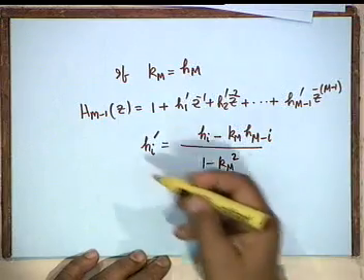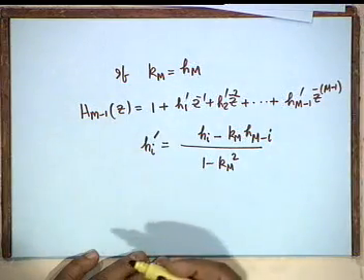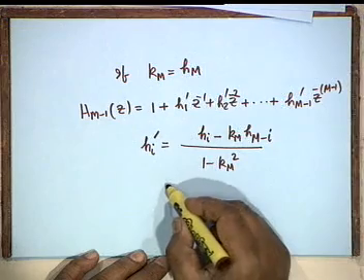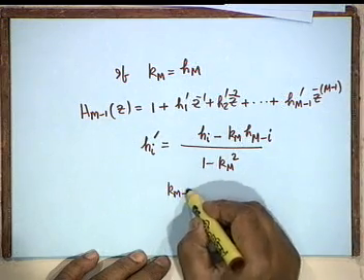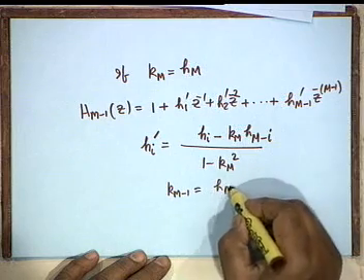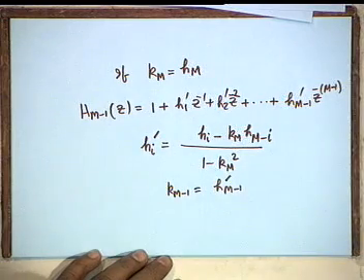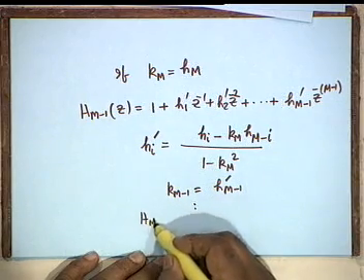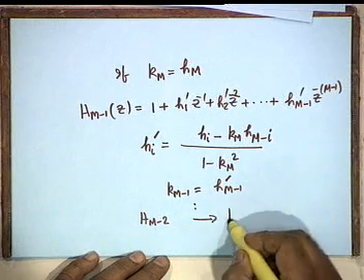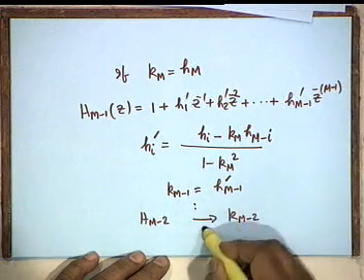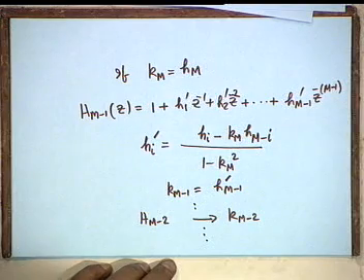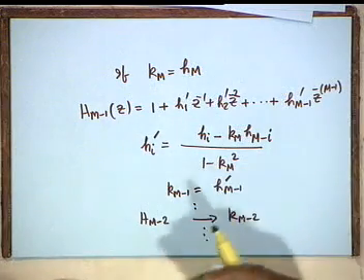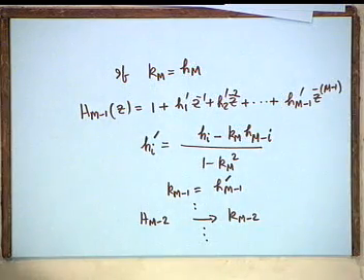And if I have obtained Hm minus 1, okay, what is now the Km minus 1 obviously is equal to h m minus 1 prime. Then the next step would be you derive H m minus 2, from which you derive Km minus 2 and repeat till you exhaust the function, and you have obtained all the coefficients, all the lattice coefficients. Okay.